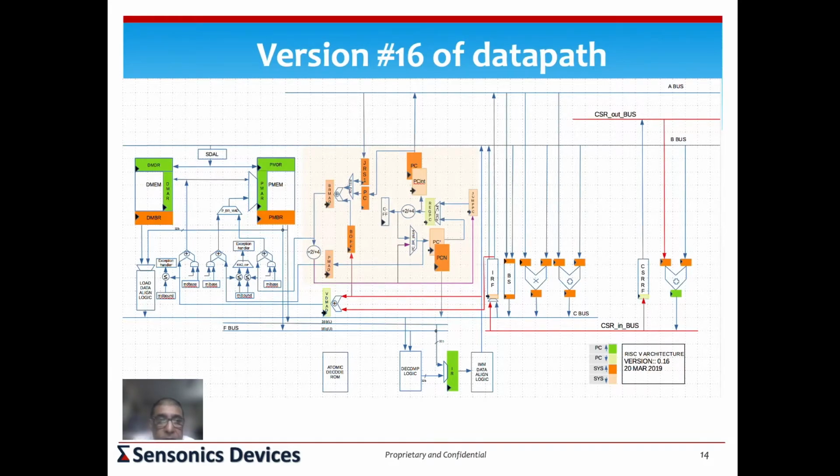And similarly, if it is readable, you could actually do a load store from that. So all that mechanism exists in RISC-V, and you'll have to define that in terms of the register transfers that you will support, and therefore the corresponding control elements. Each one of these elements that we have shown here in this data path, I have not shown that here, but in your Excel, you will write out the control signals for each one of those.